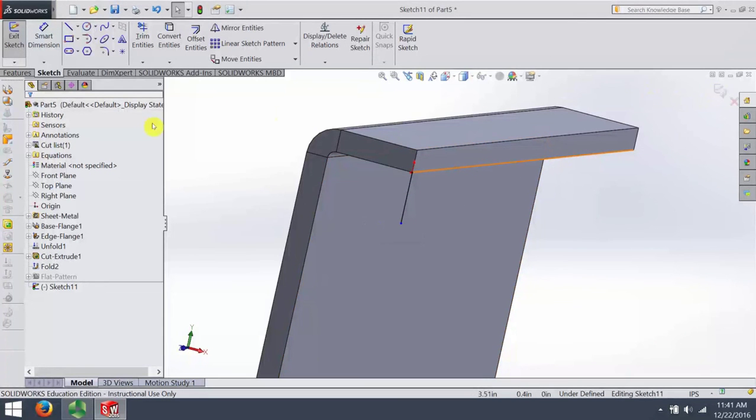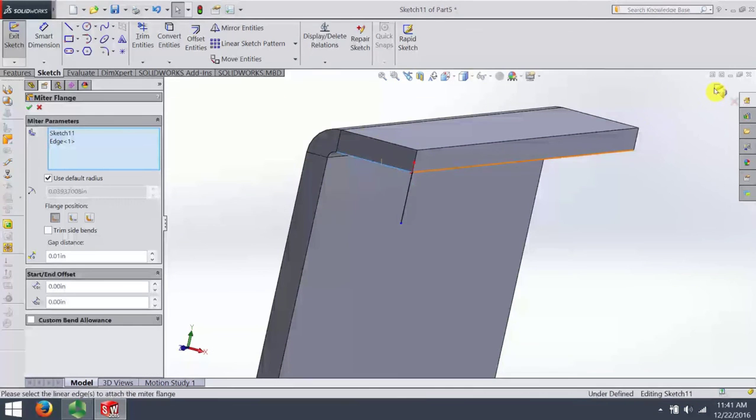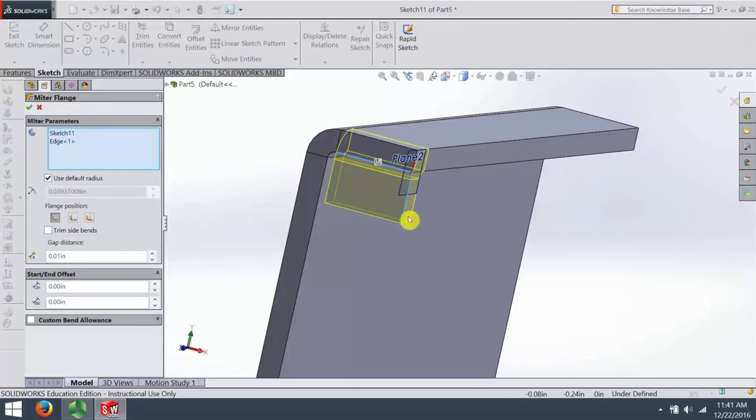And remember, I went into the miter flange command, so it knows it's sheet metal. It's not just a simple sketch. Close the sketch, and it starts to want to go around this. That is, it built one, and then notice this tool right here, propagate. Propagate, like all propagate in SolidWorks, basically means take that along the edge, follow the outline.